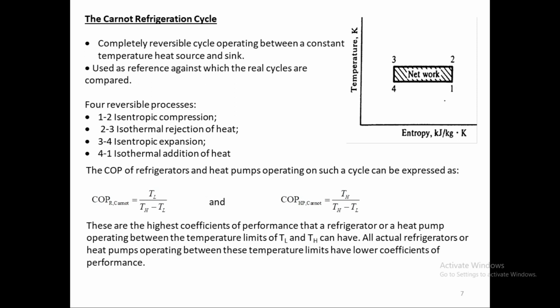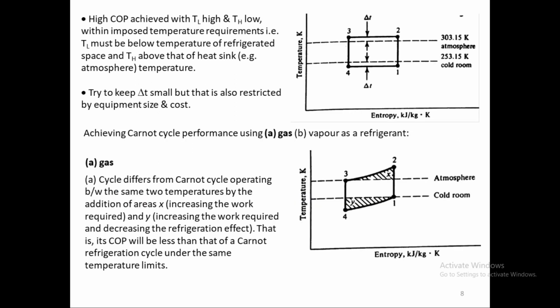Similarly, in reverse, you can think of it in the morning when you see dew formation on the leaves and on the plants, etc., on the surfaces. But the temperature of the surface and the air surrounding it is about the same. This can happen only when the surfaces are very, very large. In the case of a refrigerator machine, we cannot have such a large surface. So we need a temperature difference. That is the reason for having a delta T.